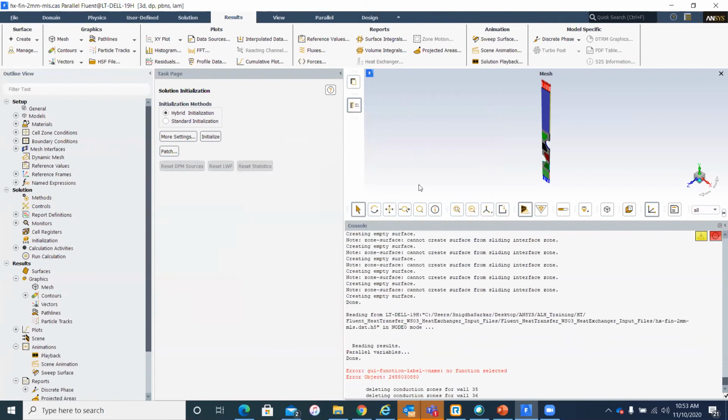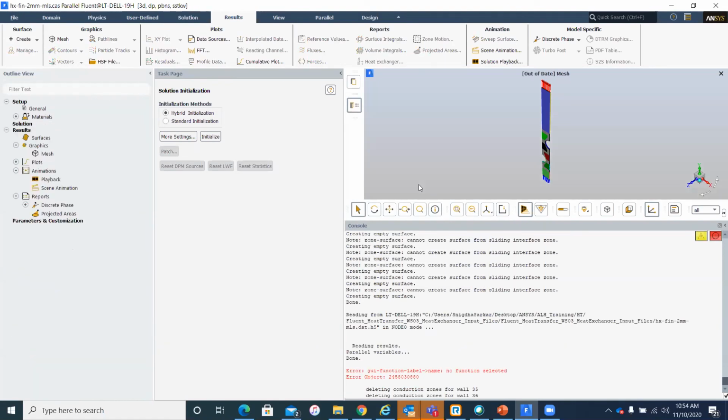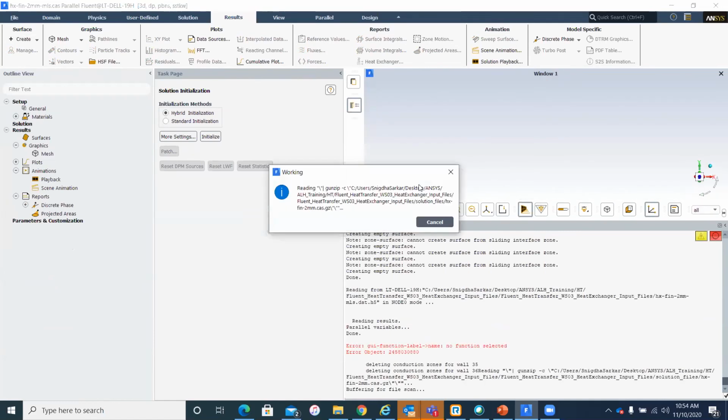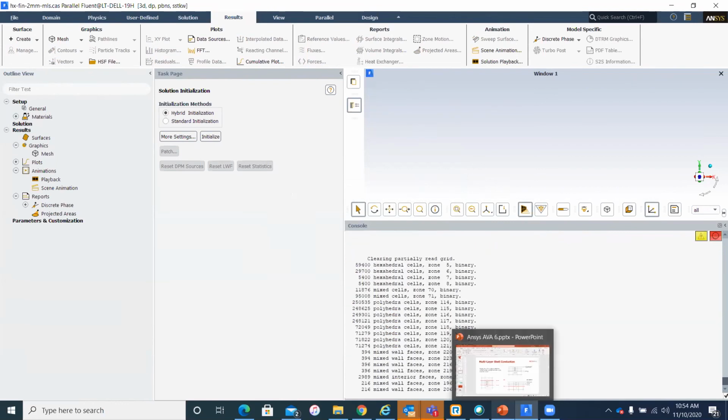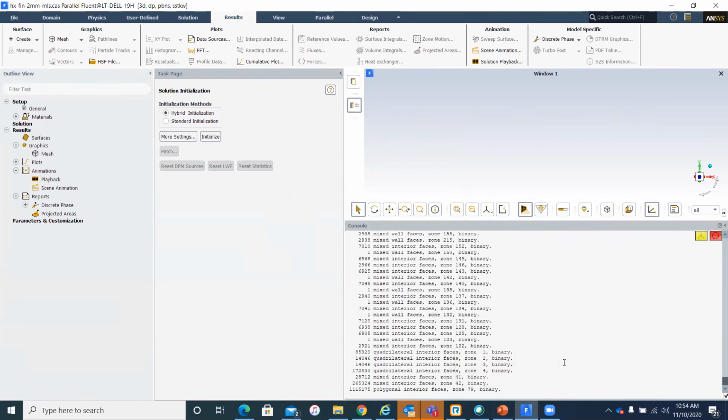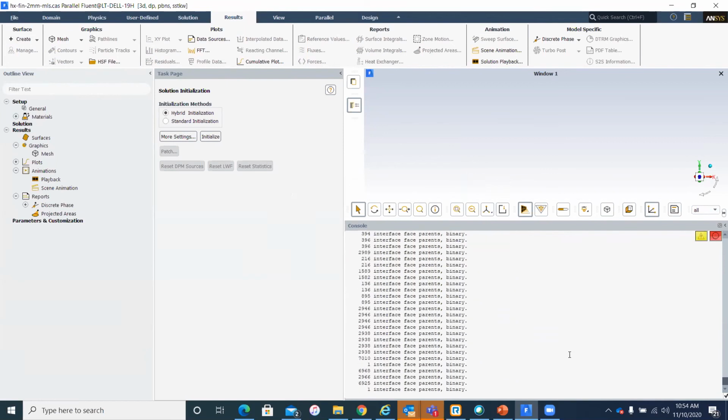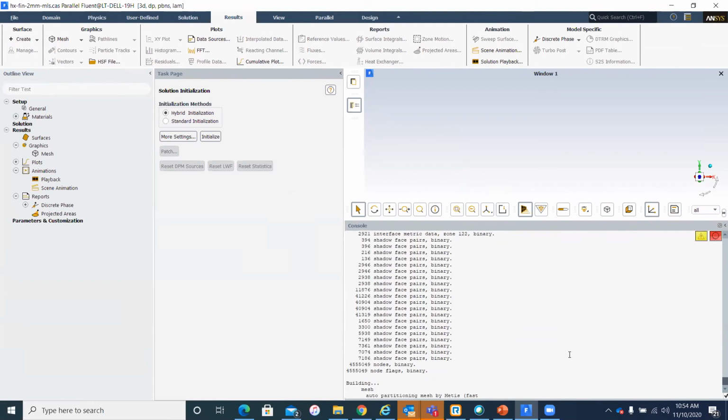The other thing to keep in mind when you're post-processing convection coefficients is to assign the correct reference values, because if I am looking at heat transfer coefficients, then my bulk temperature and my free stream temperature make a huge difference. If you change the reference values, your heat transfer coefficient changes.